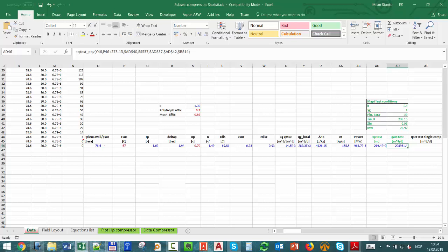So here I'm going to make a trick because I don't want to mess with my sheet. So I'm just going to say, is that pressure minus, and what delta should we use for the choke? We can just try, okay? Let's say maybe 30 bar. Let me put here just 30 bar. And if I did my calculations correct, now that number should increase. Okay, if you remember before it was 200 and now it's 5.